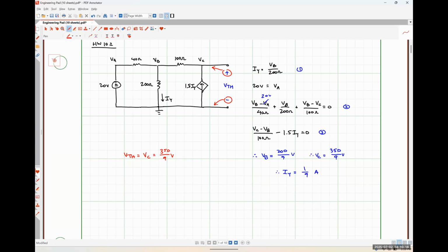So now we have a choice. We can either solve for I Norton, and then use the ratio of V Thevenin to I Norton to solve for RTH, or we can use a test source method in order to solve for RTH directly. I'm actually going to wind up doing both just so that we can use it to check our work and also to give you guys a little bit more practice using the test source method. So let's find our Norton current next.